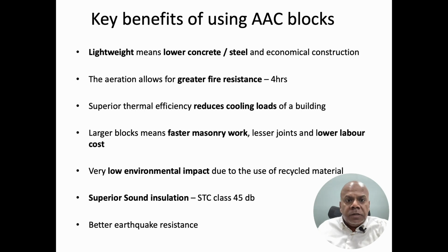Larger blocks, faster masonry work, less joints, lower labor cost, low environmental impact because we need so much less material. You are making a lightweight block which has 1/3 the weight, so you are using 1/3 less material inside. Imagine the amount of carbon footprint we are saving.